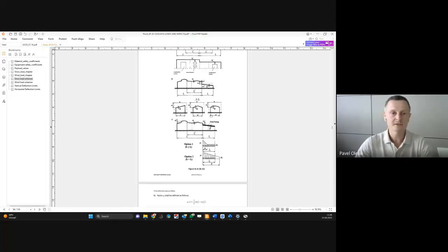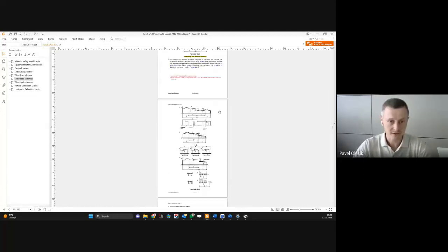And also, sometimes if we have trusses, in our manuals it's written that to correctly calculate diagonals of this truss in the middle of the truss, we must give snow load for the left side of the truss separately, and the right side is without any load, and then the reverse for the right side of the truss. And by this way, we will get forces in the middle of the truss for diagonals 2-3 times bigger than for regular snow load. It sometimes also has some effect.